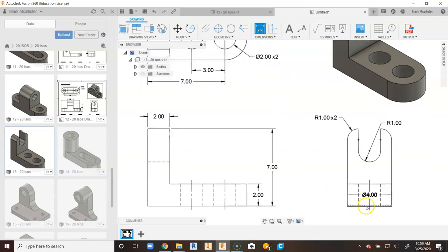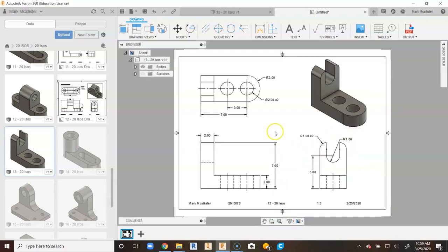You know, that radius of 1 arc that's right here, and we're just going to come up to our center mark that we made and drag that out. And we can tell now the distance from that point up to the top is 2, and we can infer that from another dimension. We have 2 down here at the bottom. We really don't need any other height dimensions to fully communicate how to create this drawing. So this right here is a fully dimensioned sketch.